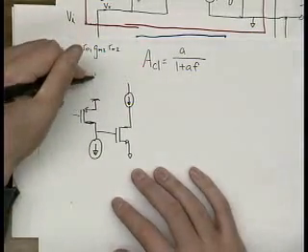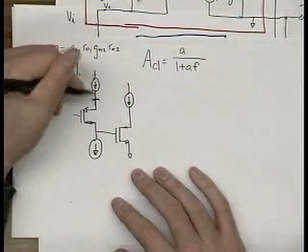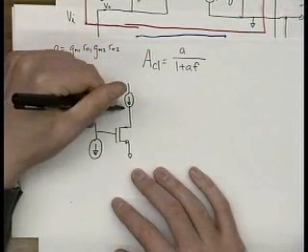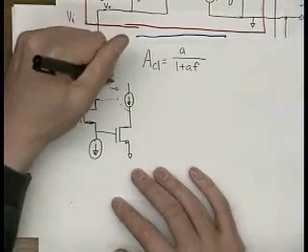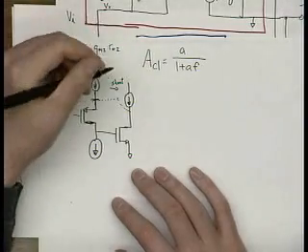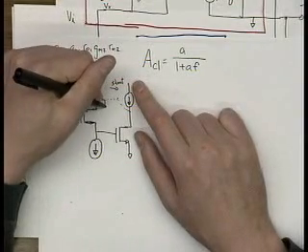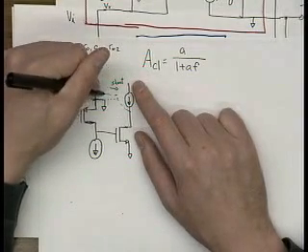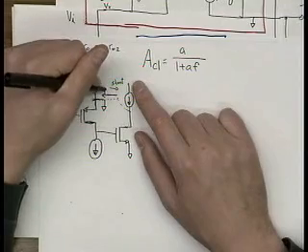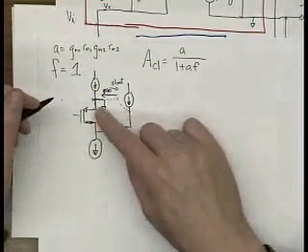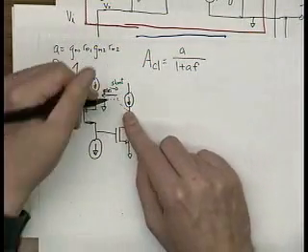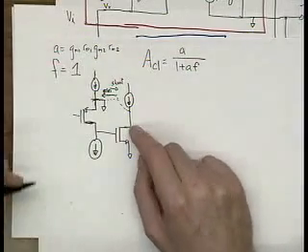And really what we have is this current here, and this dotted line connection to here. We know that way is a shunt, so looking in this way, it looks like a short. And we know that dotted line that way is a series, so looking that way, we leave it open. So when we break the loop, this side becomes a short, this side becomes an open.